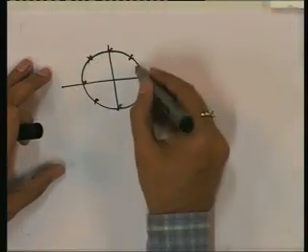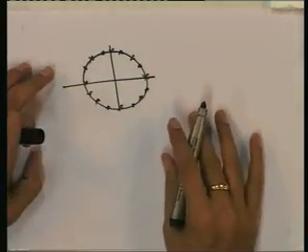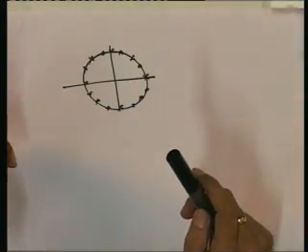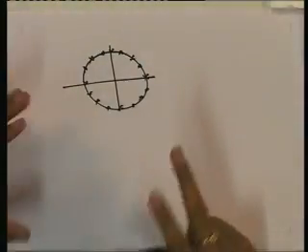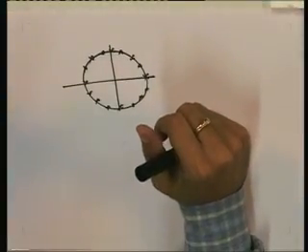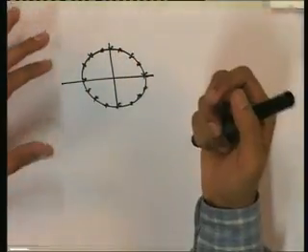For the 8 PSK signal set we have these points, for 16 PSK we have these points, and so on. And we have also discussed how to increase the number of points in PSK. If we want to keep the probability of error the same, we have to increase the radius of the circle, that is, increase the transmitted energy, because we want the same distance but more points on the circle. If we don't want to increase the energy, we have to put more points on the same circle, and as a result the probability of error will increase because the distance between the points is decreasing.